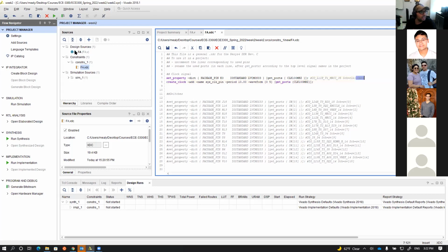It depends on the name inside the file. I'm gonna change the port here. We are not using it so far, but I'm just showing you what I have. We are not using it now, but we're gonna use it. So far, so good? Yep. So if you would like to use the clock internally, which is 100 megahertz, you have to uncomment these 2 lines. We don't need them now, so we're gonna comment them out.